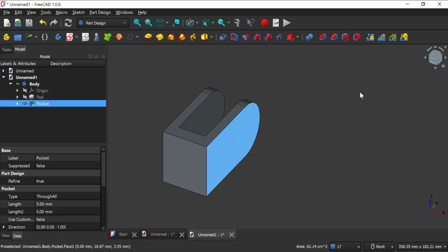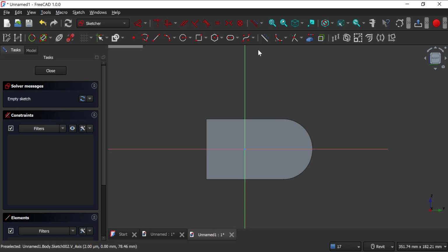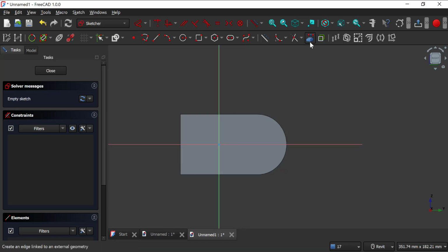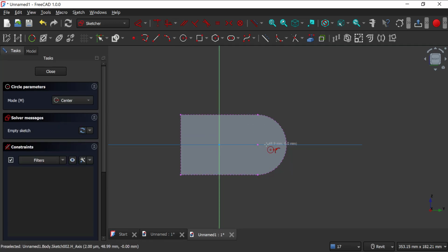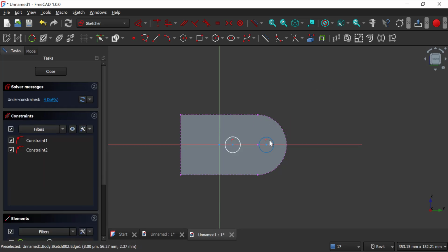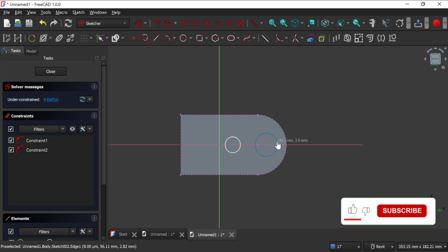So let's refer from our axis. Select this plane, create sketch. Okay. So reference this geometry, this line, this line, this line, and this arc. Okay, we are done. We need to create a circle along this plane. Okay, and create another circle along the same plane. Okay, so these circles coincide with this plane. So if you move, it only moves along this axis.